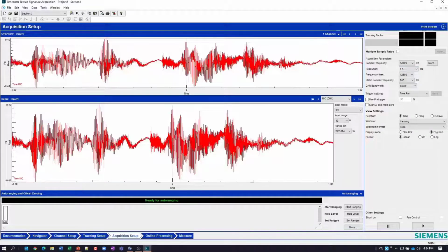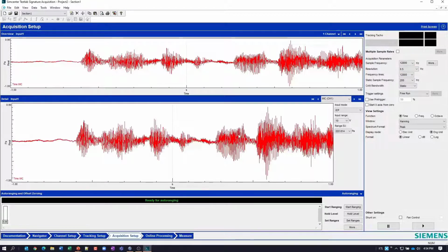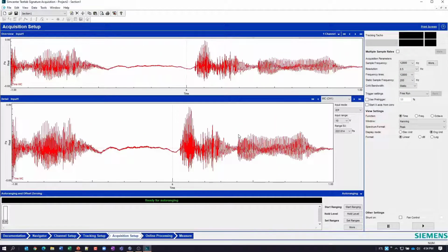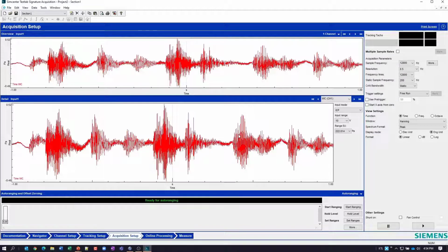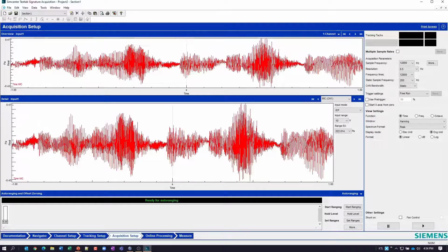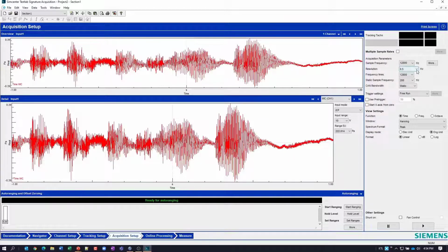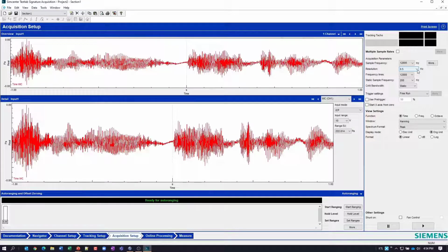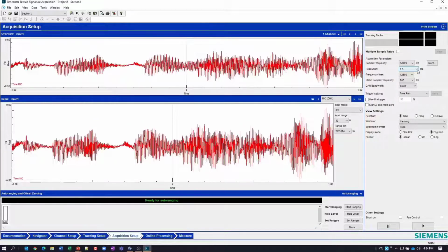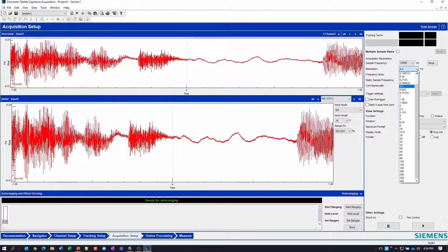Okay, so for 25 averages, it would be 2 times 25, about 50 seconds. Those are 50% overlap, so it'll be less than that, but just simple math here. So I need to keep that in mind. Ultimately, the length of my test is going to be determined not only by the number of averages, but how much time each average takes.